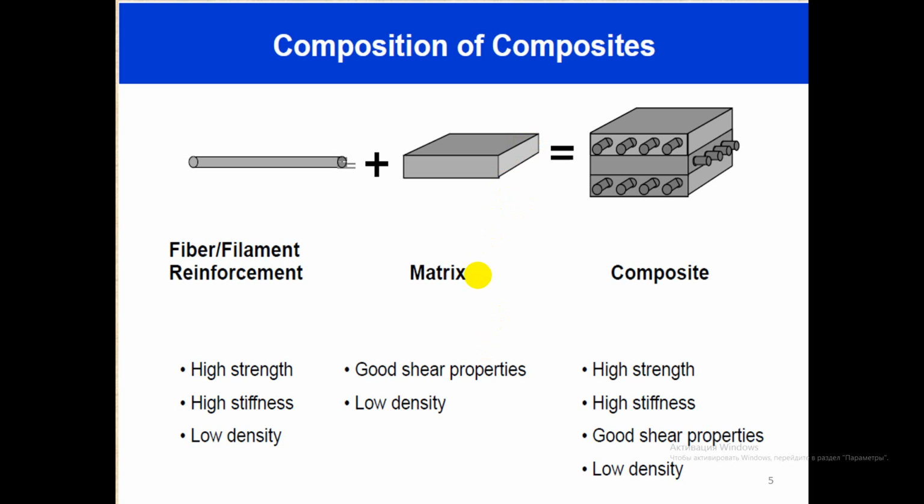Fiber reinforced polymer consists of fibers, carbon, aramid, or glass, bonded together with a polymer matrix, epoxy, polyester, or vinyl ester. The necessity of using FRP for strengthening buildings and structures is due to the internal properties of the material, such as a high strength to weight ratio and corrosion resistance.